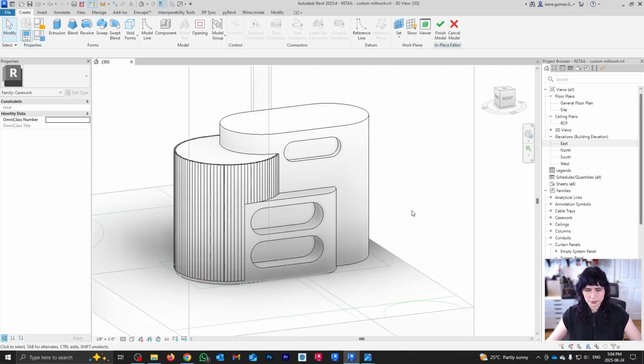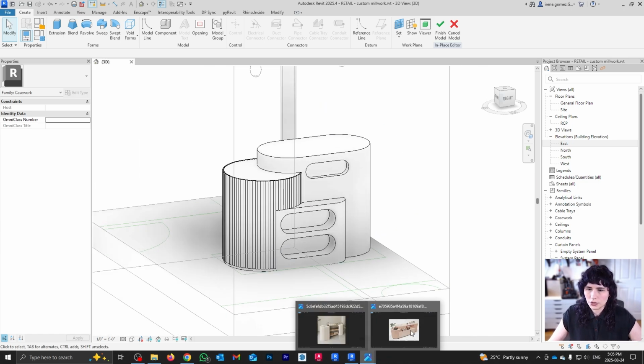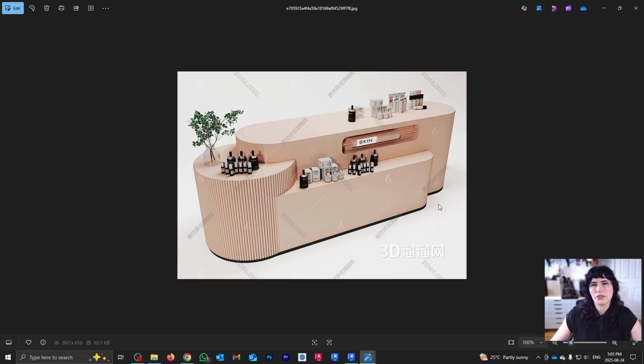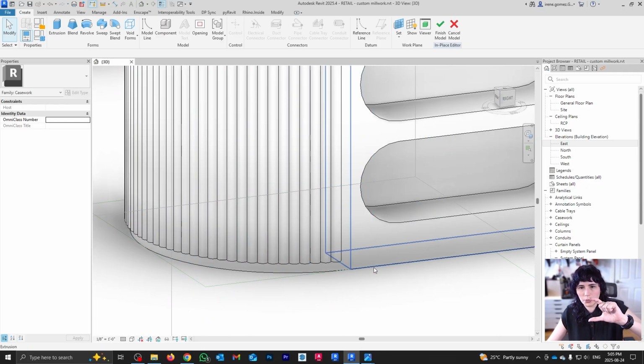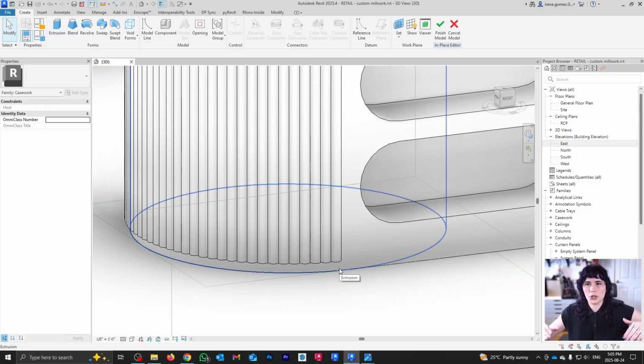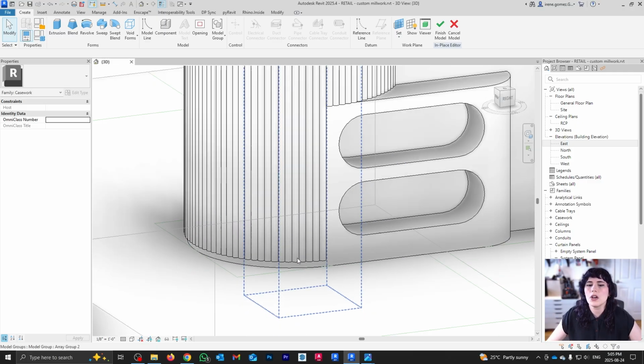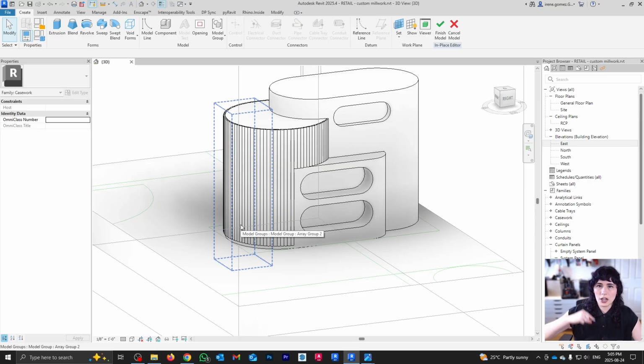Okay, perfect. So now, to add a little bit more complexity and just show a few more things that you can do, so not everything has to be extrusions, let's do a sweep. I absolutely love working with sweeps. So first of all, if you remember, I was talking about the fact that you have here a reveal. So there's 2 ways that you could have done that reveal. One option is that you could have just basically the same way that I did with this guy, that my slats start a little bit above. I could make it so all of these geometries start 1 inch above and then model basically what would be the base. Or the other way that you can do it is you can do a void sweep.